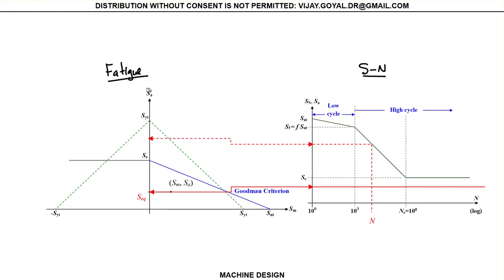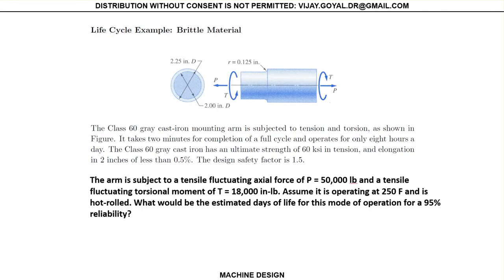And you plot this SA versus SM, and note that every value here under your endurance limit will be a value that corresponds here. Any value above the endurance limit is a value that corresponds here. So this is in general, and if this is yield, if it's ductile materials, it will be ultimate if it is brittle material.